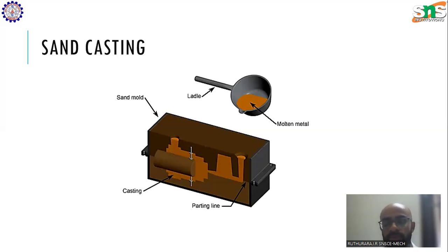And coal is used to get a smooth texture. Coal is very soft in nature, so it can be used to get a smooth finish. That's why we are combining these three. Even though the name indicates it's green sand, it will be black in color because of the presence of clay and coal. So that sand is poured into these boxes, cope and drag.